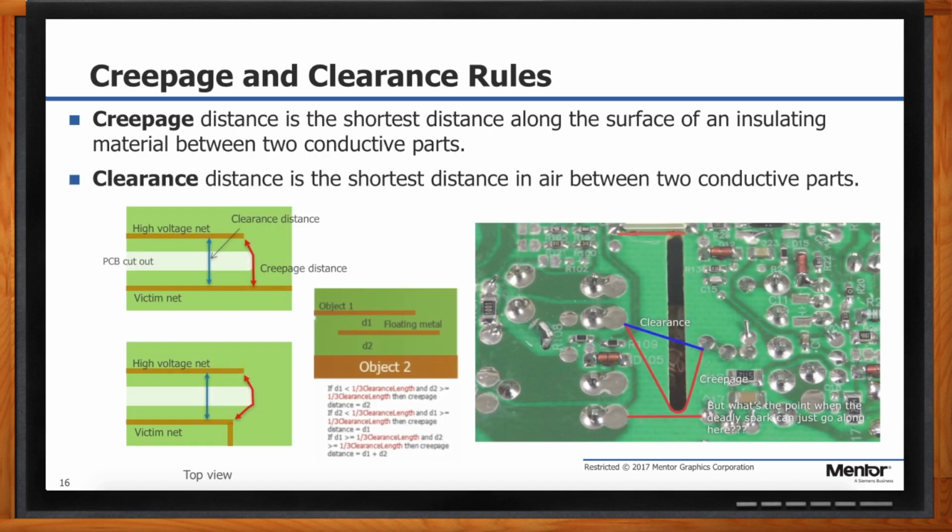This is more common in household application circuits where we're using high voltage in the public sector, and in the private sector with the mil-aero engineers, they have to deal with high voltage, safety issues, and tight enclosed spaces. So this creepage problem is very, very tedious to check for.